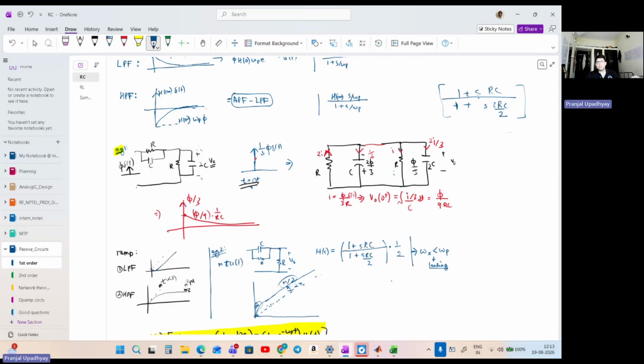Now, the particular behavior of the circuit at DC: at DC, only half the magnitude will be able to pass, right? And at infinite frequency, one third of the magnitude will be able to pass. And now, yes, we have sketched the correct transfer function, right? So whenever you're trying to find a transfer function by inspection, you can always do these kind of sanity checks. So that was the transfer function of that particular circuit.